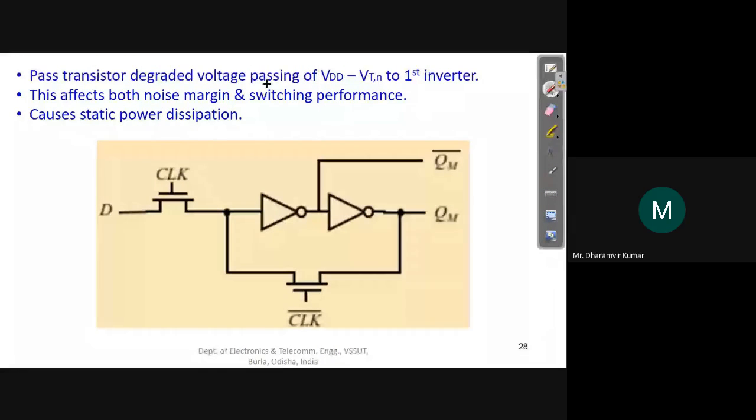So there the load was 4 for the clock signal, and this is one more implementation, but this is using pass transistors. So this is one pass transistor, this is another pass transistor, which is doing the same thing. The same positive latch is being built here, but using pass transistors. What was the goal?